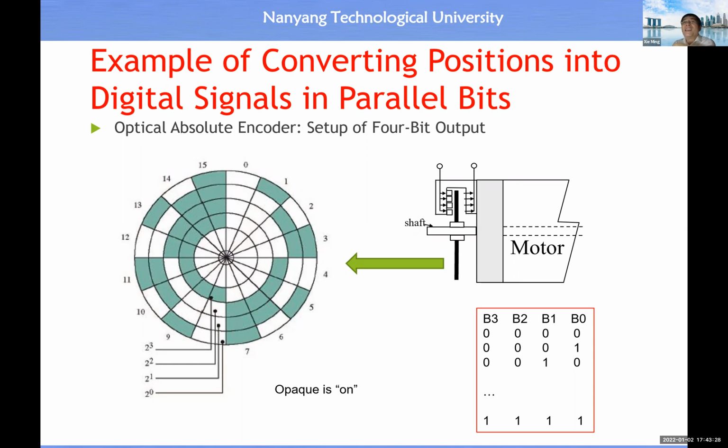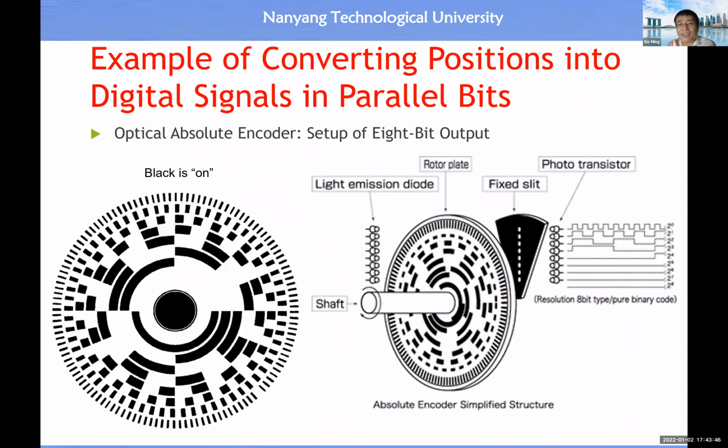Normally, for this type of conversion, we use 14 bits, so 2 ports is good enough. It's more than good enough to input 16 bits in total at each time. Then this is a solution with 8 photocells. With 8 photocells, we should be able to measure 256 positions.